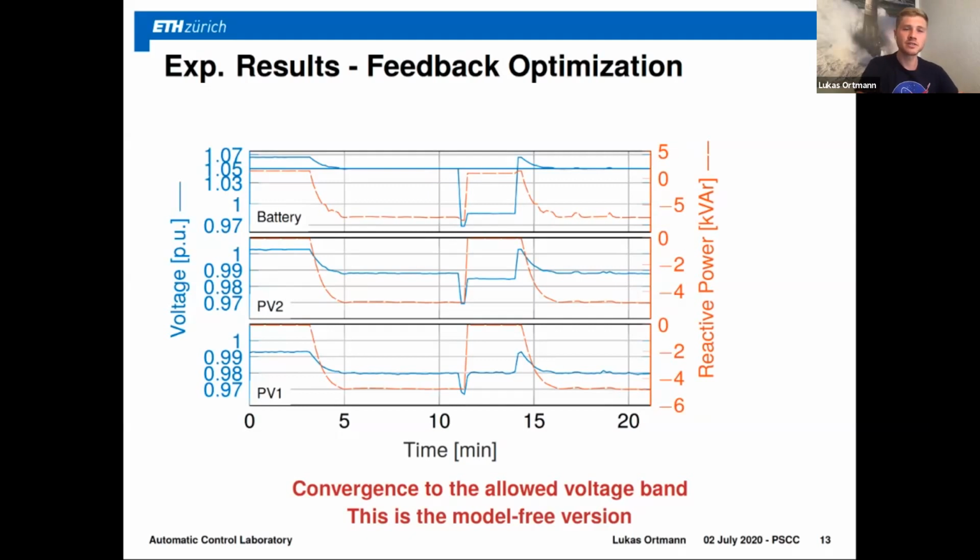So first of all, I actually think that this could be an advantage. If you're able to control your distribution grid to behave in a certain way, then you can actually start using it to provide auxiliary services to the transmission grid. So for example, if the transmission grid has some voltage problems or some overcurrent problems, they could ask a certain part of the distribution grid to provide certain reactive power flows, and with them you could maybe solve your overvoltage or overcurrent problems in the transmission grid.